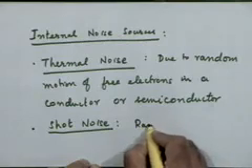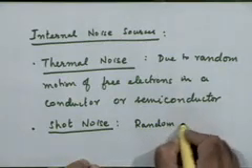And again, these charge carriers, and now we are not talking of only electron motion, we are talking of any kind of charge carrier that you might have. The arrival of any one of these charge carriers at a particular point will be totally random again, right? So that kind of randomness also generates shot noise. Basically this is due to what we call random arrival of charge carriers.